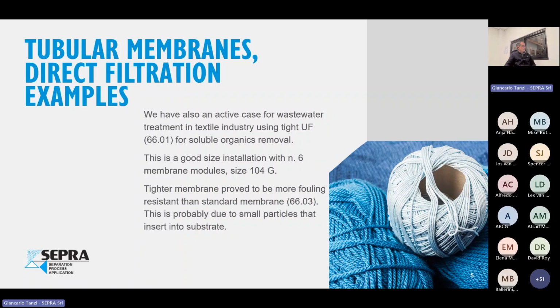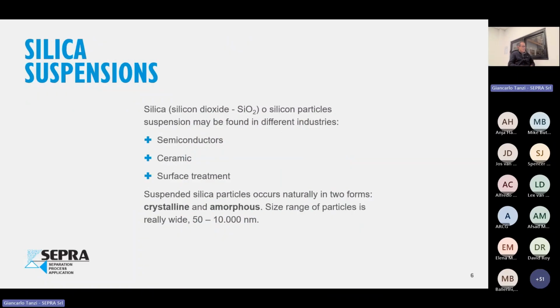And now I'm focusing on a special case, but it's not so special, because we are going really deep into the topic of pure particle filtration, where it's still cross flow, but the cross flow is purely working as a filter. There is not much in terms of organic stuff involved. There is no biological treatment. There are particles and there is a filter.